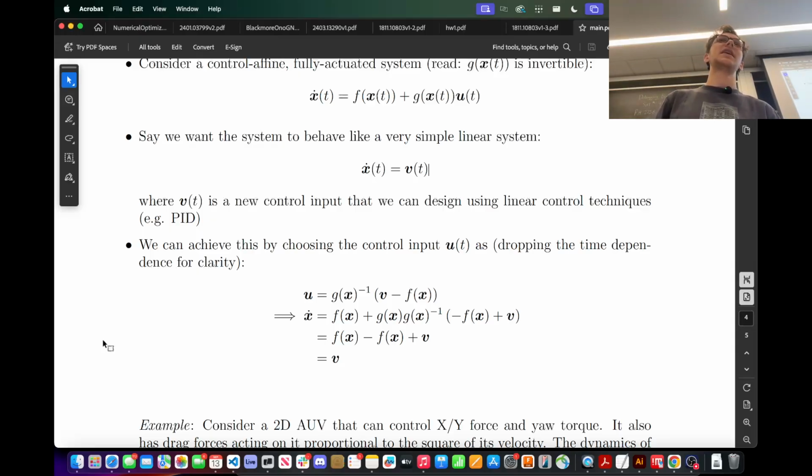Unless you have a big manipulator on the vehicle that changes the geometry of the vehicle a lot, then we're going to take that into account. If it makes the vehicle weigh a lot more, we need to know that. If it's going to change the inertia of the vehicle a lot, we need to know that. Also, with hydrodynamic damping and hydrostatic forces, anytime you change the vehicle geometry, it changes those damping parameters.